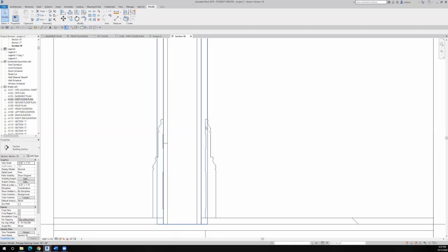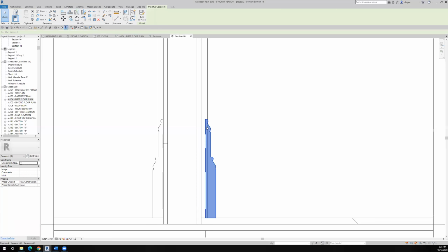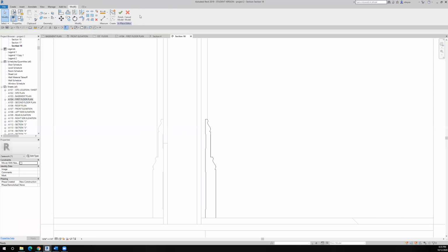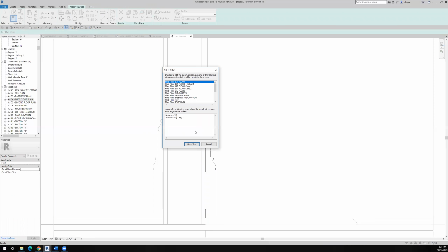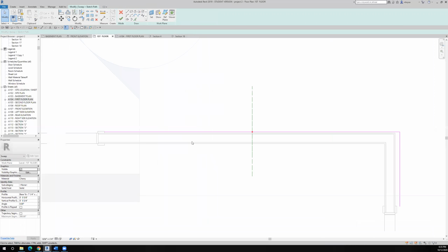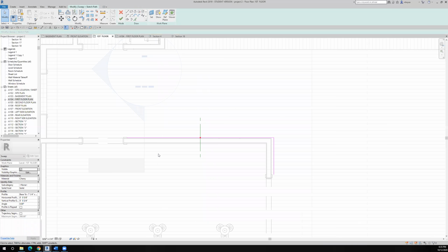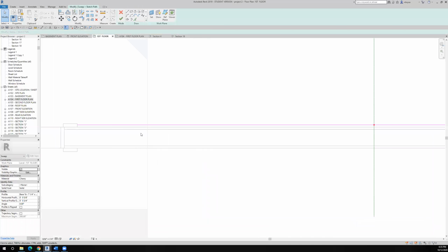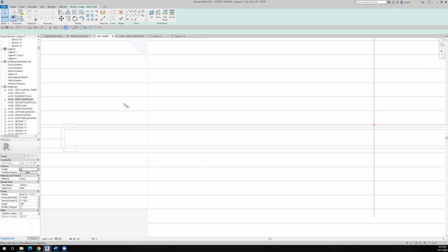All right, now this guy, edit this in place, edit the sweep, sketch the path, go to the first floor, and let's line him up.